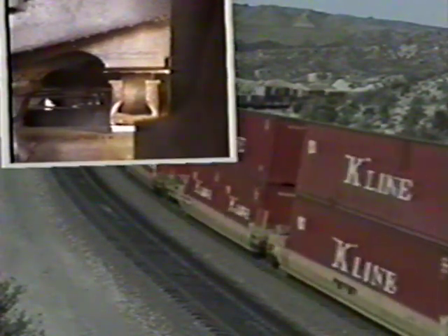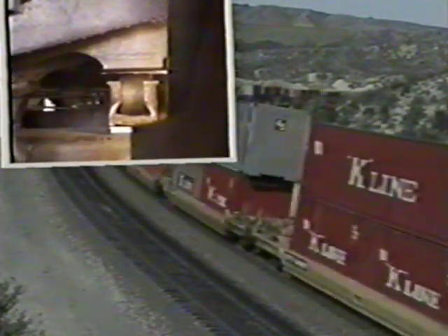Problems that cause excessive center bowl turning resistance include the presence of rust and corrosion, mechanical interference from inadequate clearance, out-of-round components, broken center bowl liners, or fasteners that project into the center bowl center plate area.